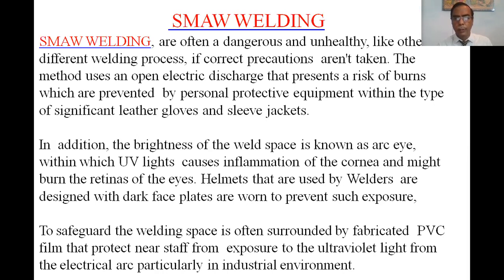SMAW can be dangerous and unhealthy, like other welding processes, if correct precautions are not taken. The method uses an open electric discharge that presents a risk of burning, which is prevented by personal protective equipment such as heavy leather gloves and protective jackets. In addition, the brightness of the weld area can cause arc eye, in which ultraviolet light causes inflammation of the cornea and can burn the retinas of the eye.